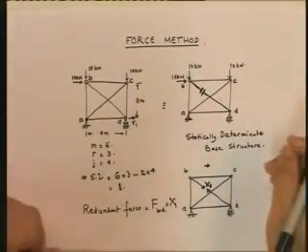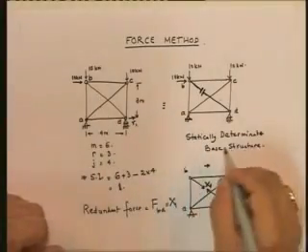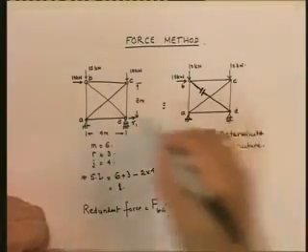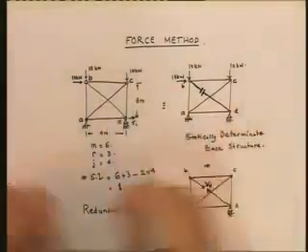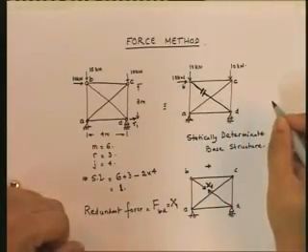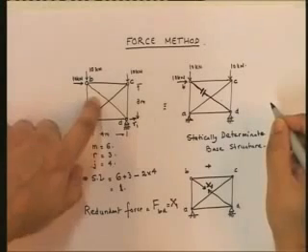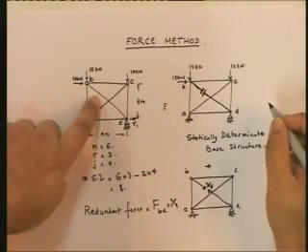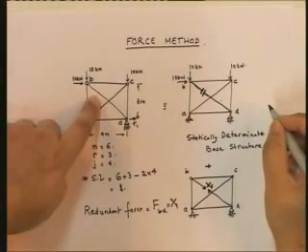We'll find that out. But in the real structure, does that happen? Do the points overlap? Does any point overlap with itself? Can't. It's a continuous member. So what does that mean? In reality, in this structure, there is no overlap or shortening. So therefore, now you understand what we get? We get what is known as a compatibility condition.